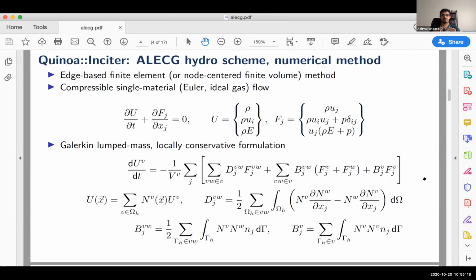And we would also have operations over elements surrounding this edge, and elements surrounding each of the nodes that constitute an edge. So there's a lot of indirect addressing is what I'm basically saying when I give you all these details. And this becomes important when we're looking at distributed memory parallel algorithms, because we need to make sure that along the process edge, we communicate all the required data structures in a consistent manner.